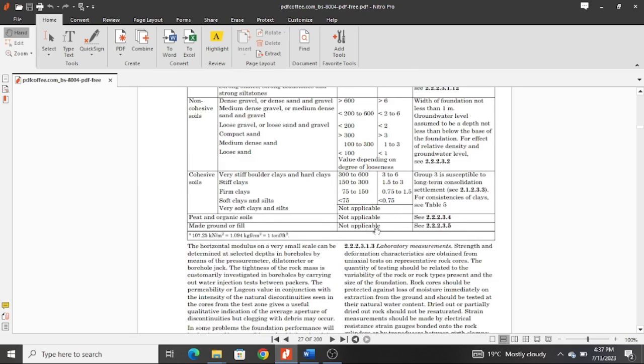These are mostly imported soils, and there are ways that you can determine whether the soils are imported or they were existing there before. So we do not do foundations on imported soils unless it is really necessary, and that is when it might require you to think of doing floating foundations or piles or any other applicable systems.